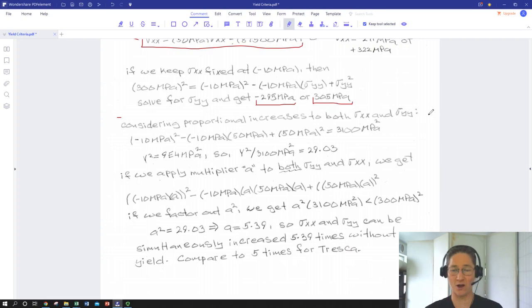And so we're going to go beyond yield, and we're not going to be looking so much at max shear, which is what makes things deform, but we're going to look at max tension or compression under which things could fail. And so for that, we'll be linking very hard back to experimental data. So we'll be using much more the principal directions of our Mohr circle, which are the things that make things fail. So stay tuned for that. And that will conclude our yield and failure section of our course discussions.